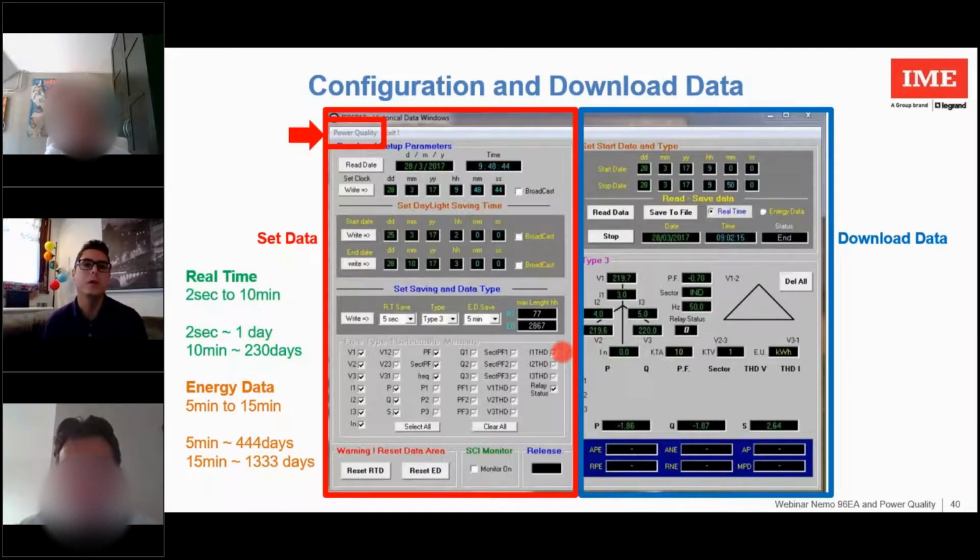For example, if you put one communication port, but 2 interfaces like the EF4E011, they can manage the traffic on the bus. Or better, also with one interface, because the interface is a multi-session interface. So when you receive 2 requests from the SCADA software, or 2 different PLCs, for example, this EF4A manages the traffic on the bus, and you get the right answer for the two requests. So one interface and one multifunction interface.